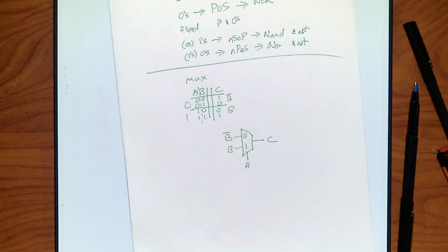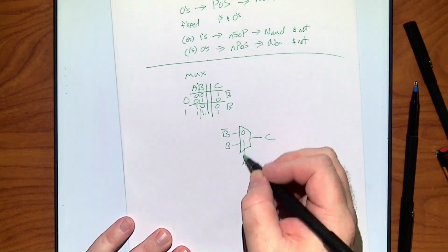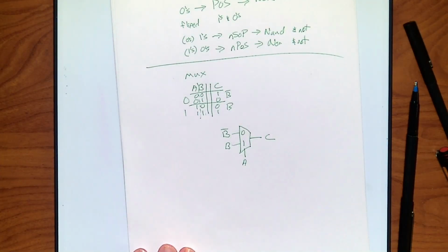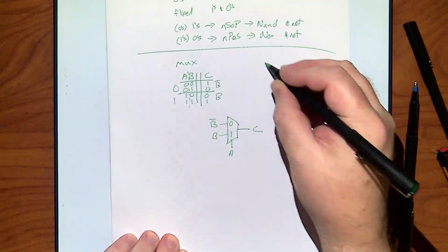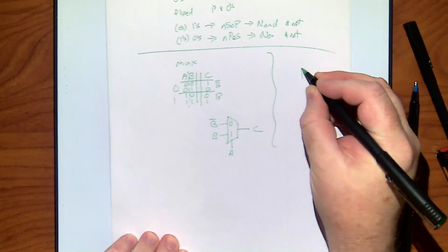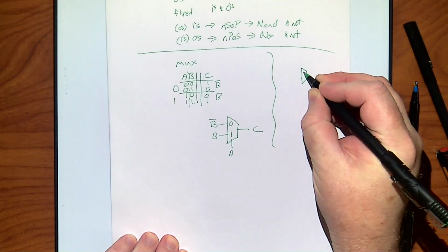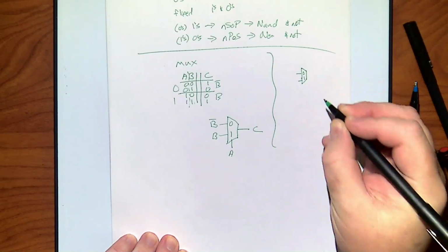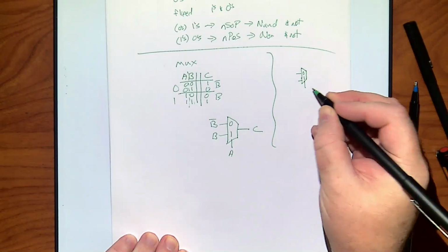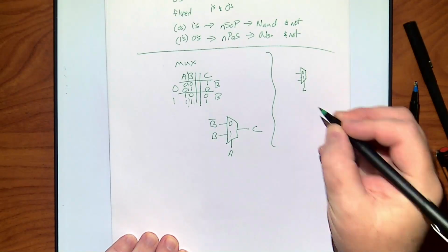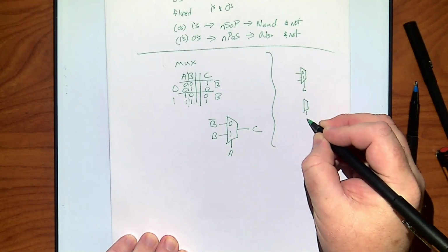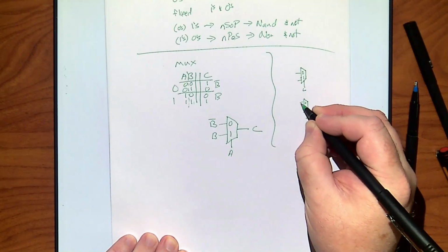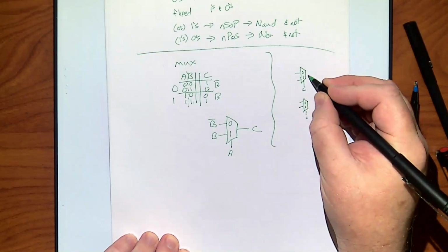What if it's a bigger function? Well, can I build a larger mux from smaller ones? Yeah, all I have to do, just as a side note, is cascade them. I've got a smaller 0, 1 here, right? With, I'm going to put L. I get two of them. Both hooked to L, right?